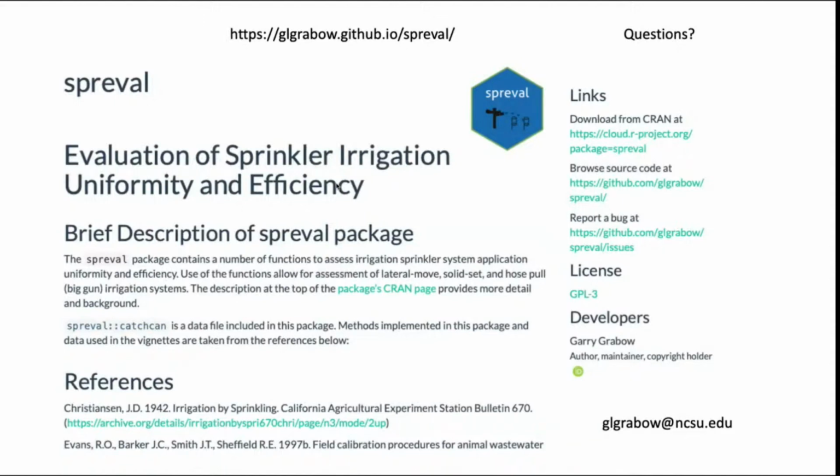There are disc filters that are a stack of discs on a spine that the water has to pass through, and that takes the sediment out. And then after it gets a certain differential pressure across those filters, it will automatically pop the spine up, expand the disc, and backflush the disc.